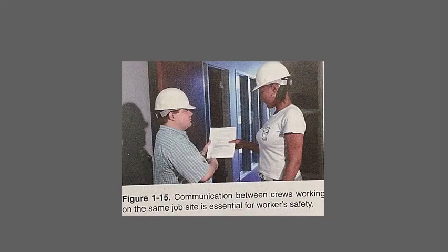Repair the hazard. Correcting hazardous situations may be as simple as practicing good housekeeping or as involved as reworking an improper installation. Some hazards may not be able to be removed at all, such as overhead power lines. Removing this hazard involves notifying others in the area by speaking to them or erecting barricades.